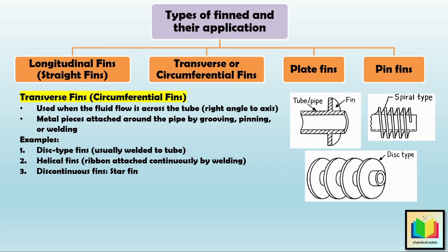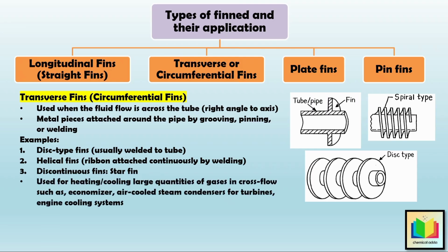Then the next point about transverse fins is, these fins are widely used for heating or cooling large quantities of gases in cross-flow, such as economizers, air-cooled steam condensers for turbines, and engine cooling systems. Then it is also used in shell and tube exchangers for gas cooling.